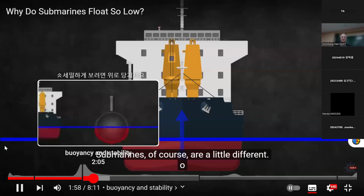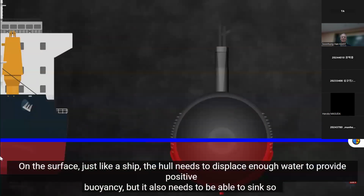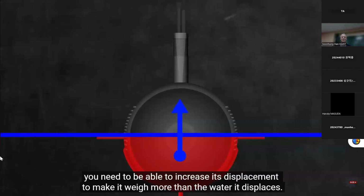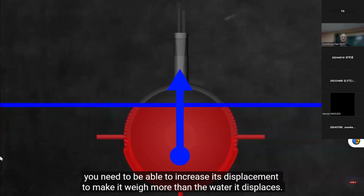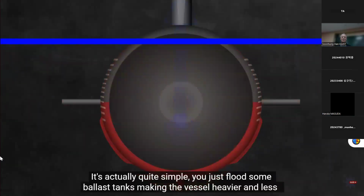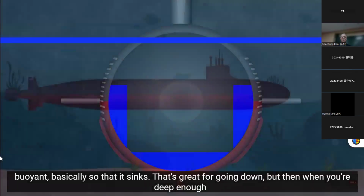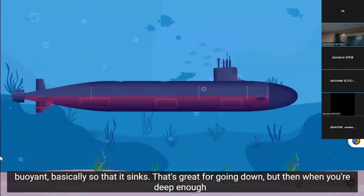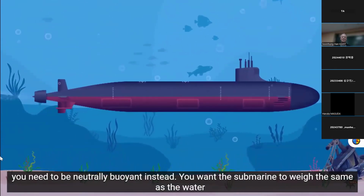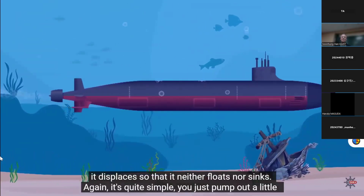On the surface, just like a ship, the hull needs to displace enough water to provide positive buoyancy, but it also needs to be able to sink, so you need to be able to increase its displacement to make it weigh more than the water it displaces. It's actually quite simple. You just flood some ballast tanks, making the vessel heavier and less buoyant, basically so that it sinks. That's great for going down, but then when you're deep enough you need to be neutrally buoyant instead. You want the submarine to weigh the same as the water it displaces, so that it neither floats nor sinks.